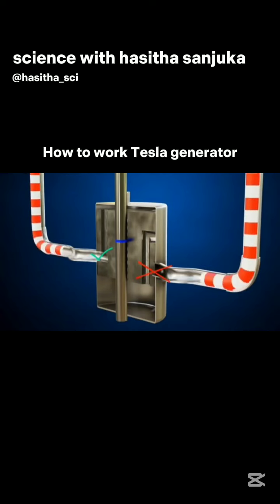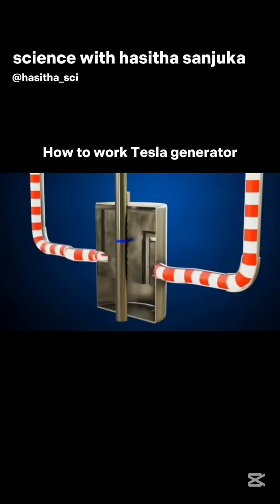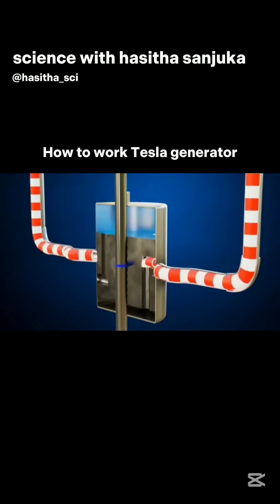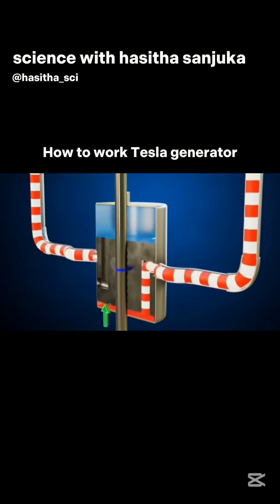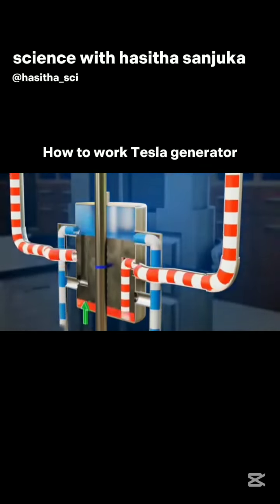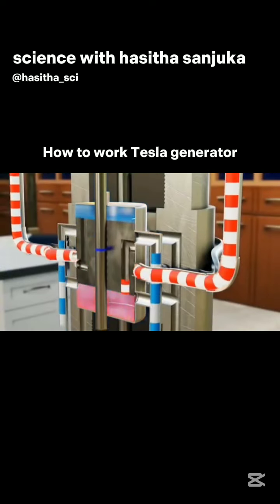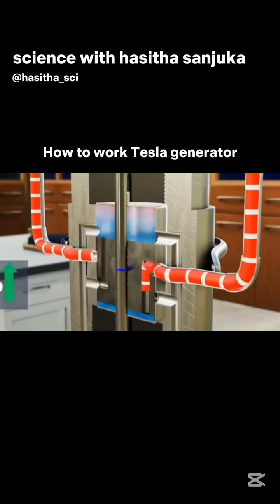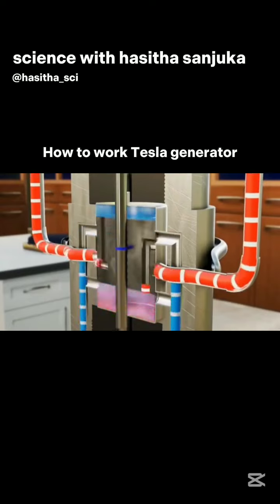When high-pressure steam enters the top of the cylinder from the left side, it forces the piston downward. Then, the right side connects, and the steam reaching the bottom forces the piston upward. Two exhaust pipes were added on each side, ultimately causing the steam engine piston to move upward. The greater the steam pressure, the faster the piston reciprocates.